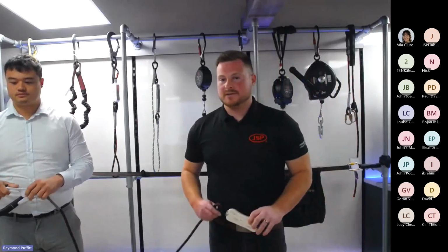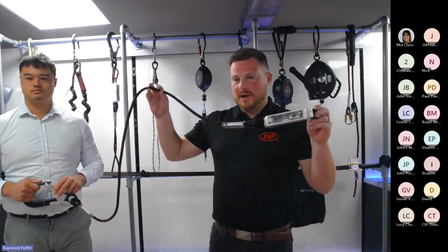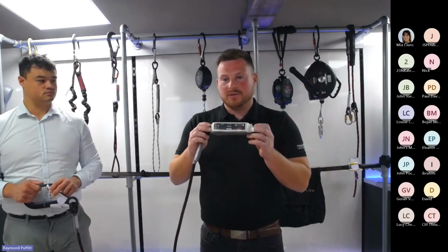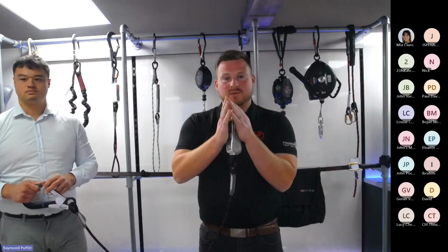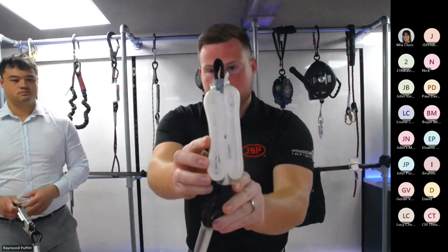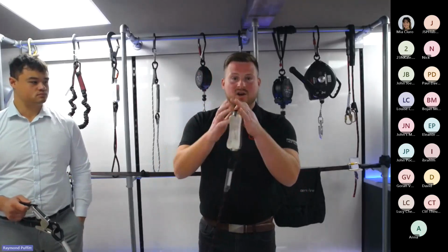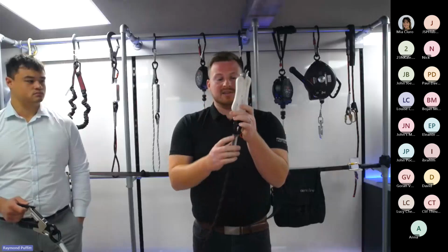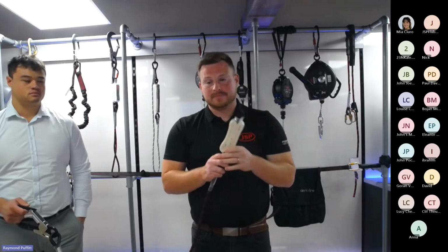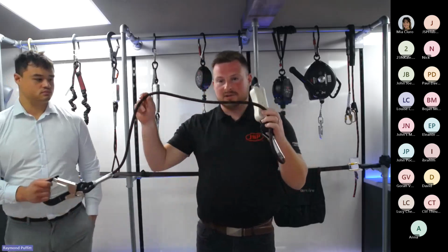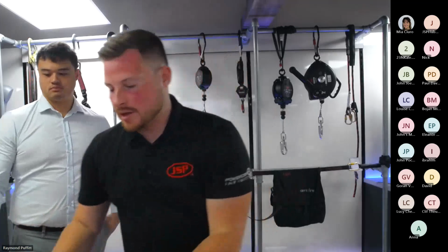Okay, so fall arrest lanyard. We always have something called the shock absorbing pack, which you can see here. The way this lanyard works, as shown in the video, is on deployment. So on impact, this shock absorber will come out. So what happens is all this webbing inside here has been sewn together and compressed into what we call the shock absorbing pack. On impact, that webbing will tear apart and deploy, as we saw on the video. And basically what we have is 1.75 meters of webbing that can come out. Obviously, we need to think about the total length of the lanyard, think about our heights, which we'll go on to show in a minute. Okay.